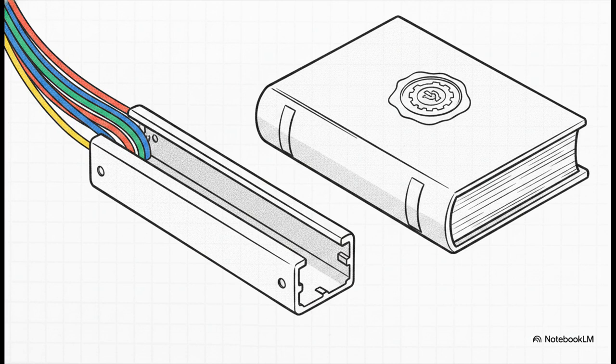The answer? It's the wiring duct. It dictates how we route conductors, separate voltage classes, and actually plan for future expansion. And here's the kicker. You can't just slap it in however you want. It's strictly governed by standards. And the true star of today's explainer is why the UL 508A standard governs this so heavily.